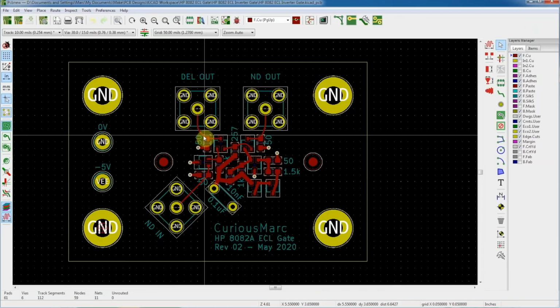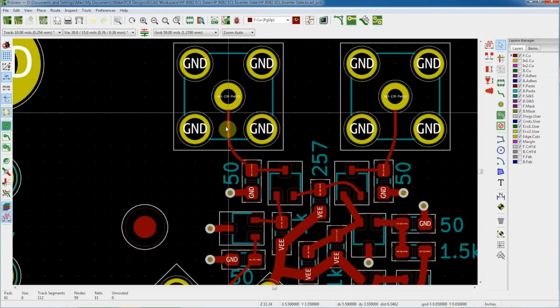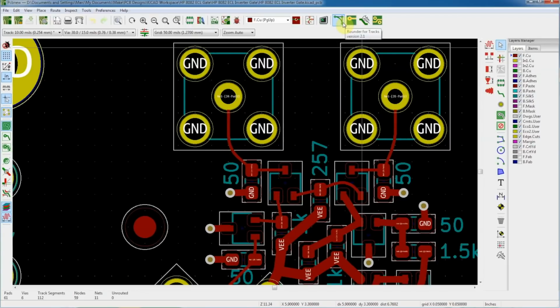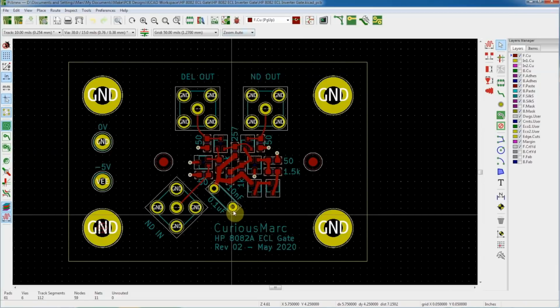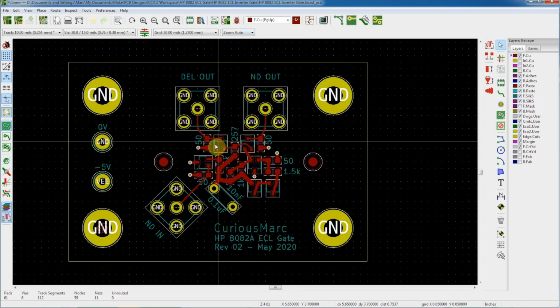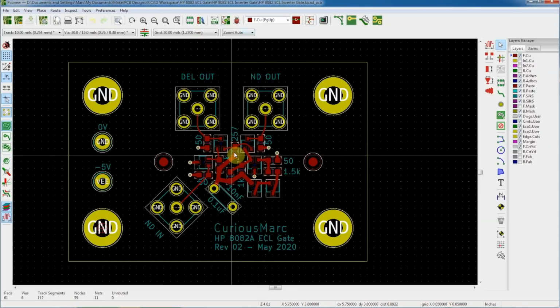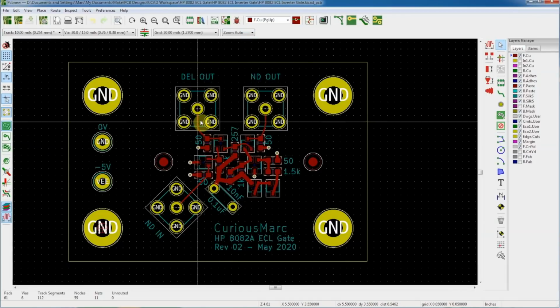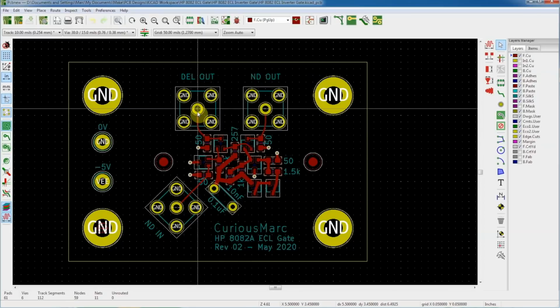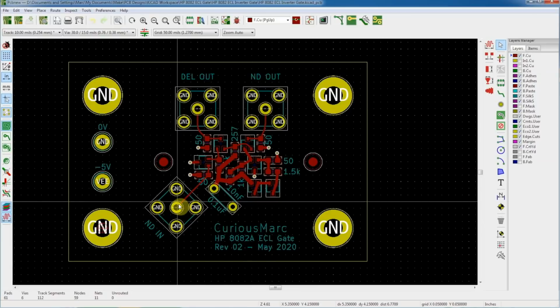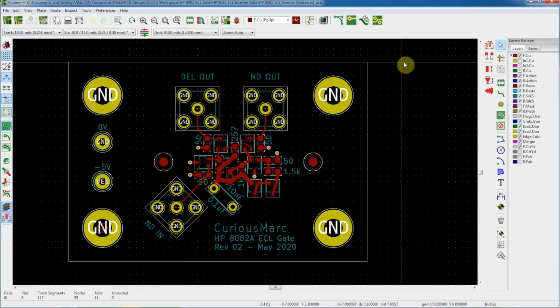Another thing you want to do to prevent impedance discontinuities and reflections is to avoid sharp bends. And I found this little external RF plugin that would make smooth bends, so that was perfect. Most of the rest is common sense to avoid stray inductance and capacitance, and put things that belong together in close proximity, like bringing the two transistors in the pair close together around their common emitter resistance. The one thing you do not want too close together is the input from the output, so I arranged the circuit so that the input is actually a fair bit away. This will reduce the chance of feedback leading to an oscillation.